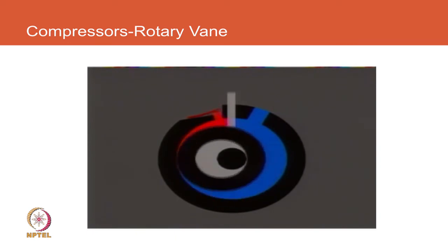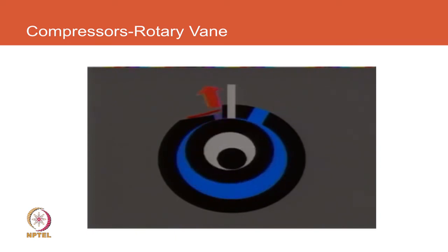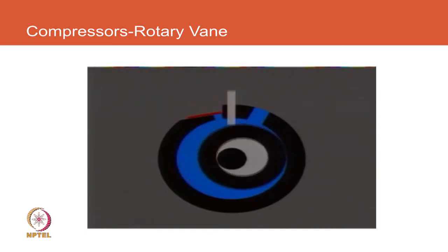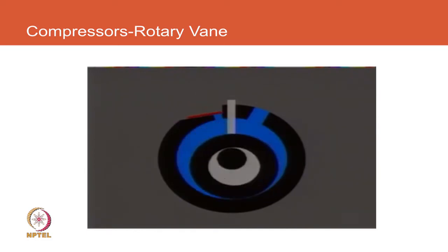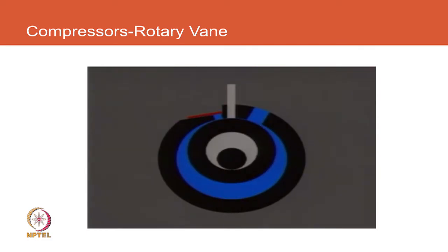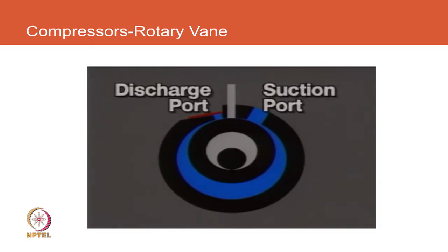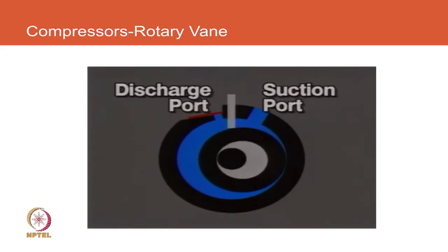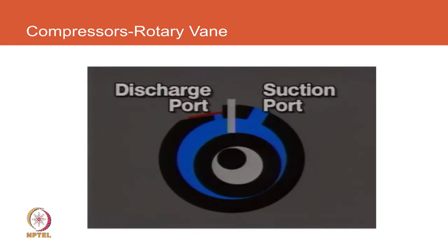The other thing to notice is that it will consist of steps of taking the entire refrigerant, fill a certain area, and then gradually compress it while the other part of the chamber is being filled with low pressure and low temperature refrigerant. So you can see this go down slowly, and here the discharge side, one on the left, the refrigerant is getting compressed and the pressure is reducing on the right hand side, which draws refrigerant from the evaporator.